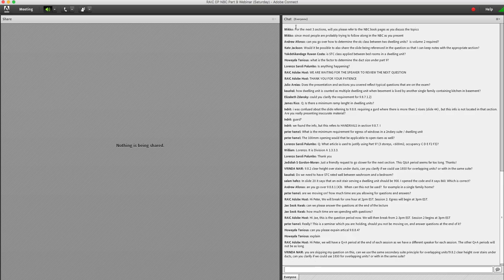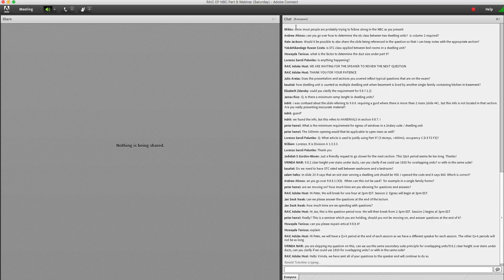Required exit stairs and public stairs serving a building of residential occupancy must be not less than 900, except if serving a single dwelling unit or a house with a secondary suite, including common spaces, where the width shall be not less than 860. Other than residential, you're back to your 900 or what's required for your occupant load. I will confirm what the slide says, and if there's any correction that needs to be made, we will do so. But that is the difference between those two dimensions.